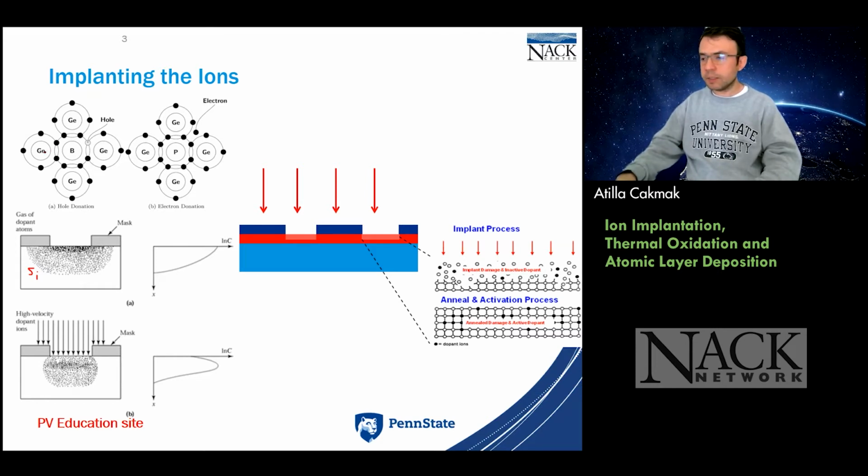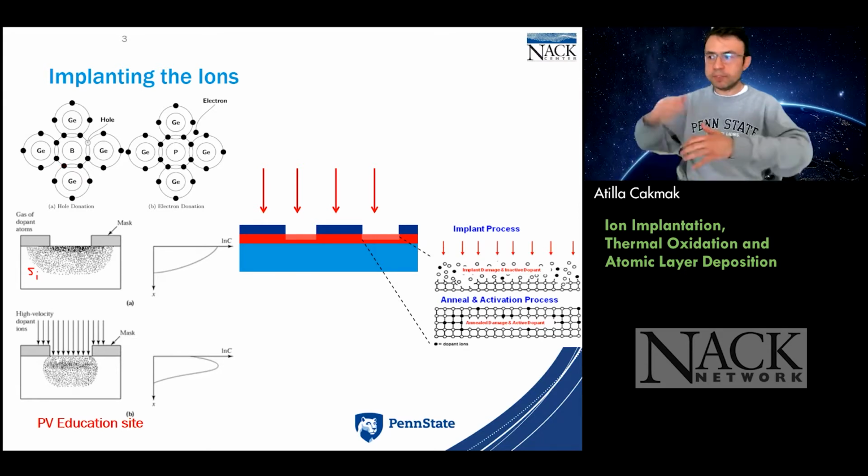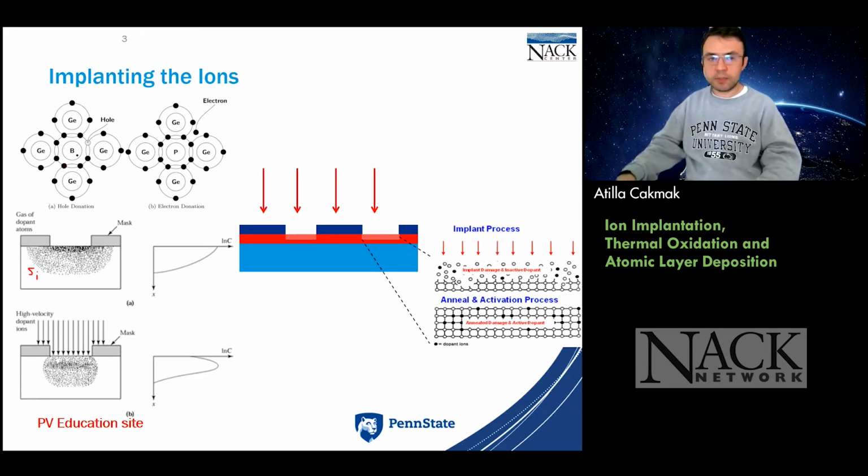So for example, let's look at another semiconductor here instead of the common silicon, but germanium. In the normal case, germanium has these 4 electrons, like you can see, and it's sharing its 4 electrons with its neighbors, doing the covalent bonds. Then let's say we have an infiltration into this crystal, into this atomic orientation, and we start to have, say, boron in the crystal. Boron will only have 3 electrons, so there is going to be an absence of an electron, a vacancy here. That's what we will be calling a hole.